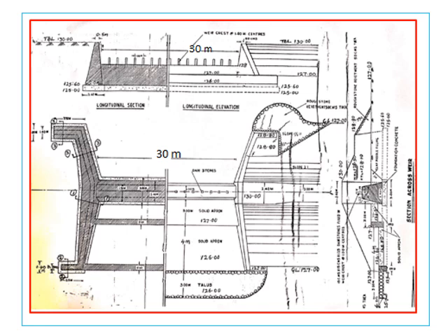Also, we expect you, before doing the drawings, to design all the components that you are required to do; it is not simply drawing. I didn't concentrate much on the earthwork calculations which you will be doing. It is a part of the survey work. After you do the survey work, you already have fixed the top of the bund. You already have the L sections and the cross sections, and all the levels are already done.